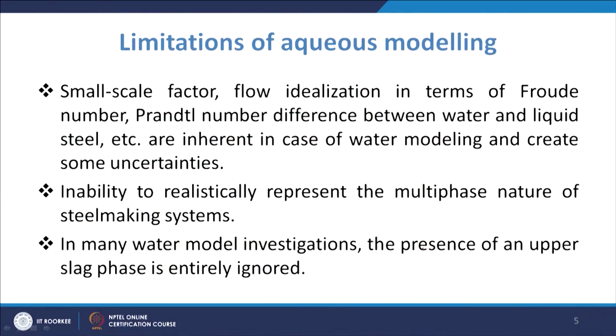Inability to realistically represent the multi-phase nature of a steel making system. So, as we see, when we talk about the steel making system, you have the molten steel at the bottom, and then you will have the presence of the slag, and then you have the air also, and they will be interacting. So, they will have interfaces in between them. So, it is basically a multi-phase system